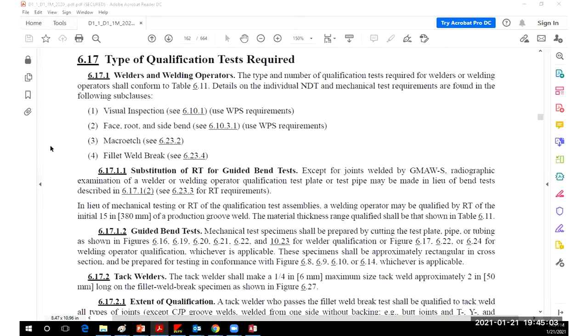Go ahead. Gerald, what are the requirements for the type of acid? I've heard some discussion about what type of acid, what strength, and how to neutralize it as far as micro etch. I know D1.1 doesn't spell it out. D1.1 is completely silent, and it doesn't reference, I can't remember what the other AWS standard is for destructive testing, but it's completely silent. Where ASME has the etchants in the back of it and tells you what's done, D1.1 just says etched. So let's look and see what it says now. They may have changed it, but I don't think so.